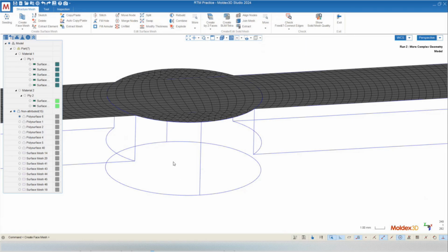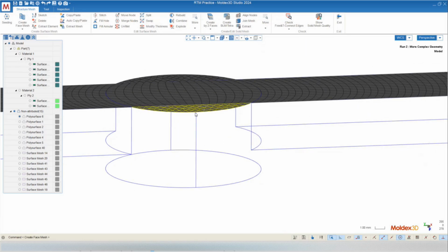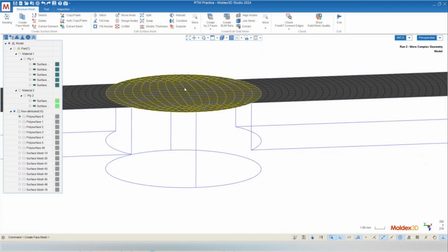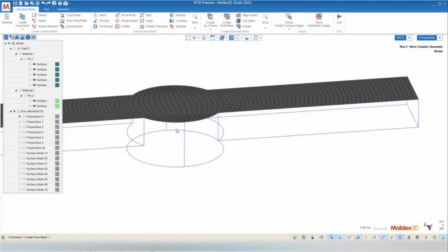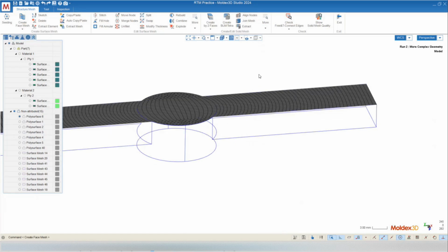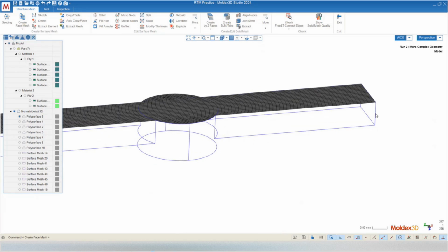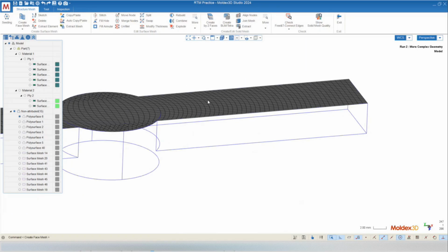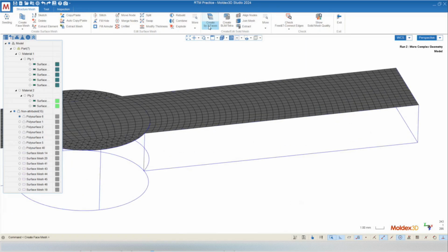But we do have to do this. This extrusion here is going to be 2 stages. We're going to go from here to this point, and then from this point down to the bottom. There's actually another tool that we can use. Up until now, what we've done is we've mapped to face. But there is another tool that we can use for a more simplistic extrusion. And that is under the Create by 2 Faces dropdown, there is a Create by Sweep.